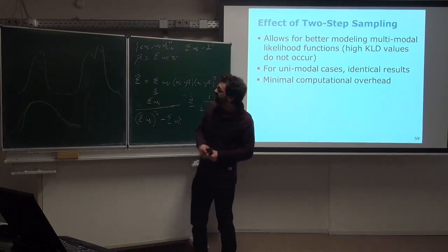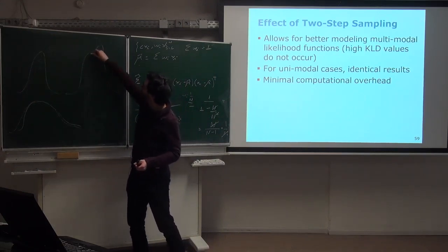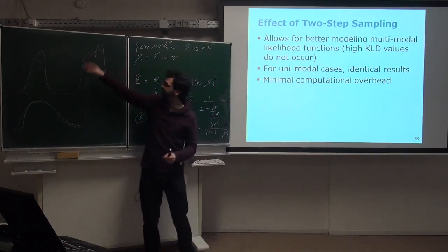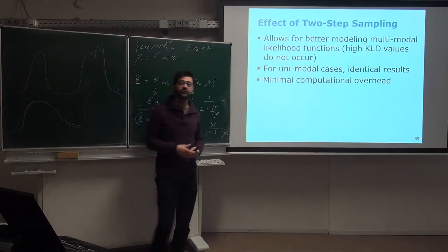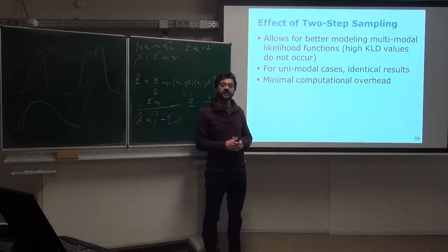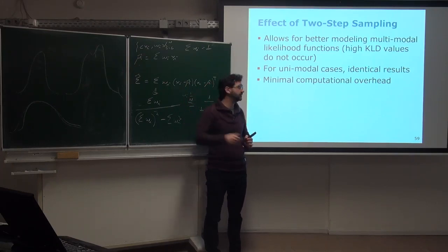In this case where it's slightly multimodal but very similar to a unimodal, you will have some differences. In this case where it's just skewed, you might have small differences but not too much. The reason is that the second step will anyway do a scan matching, so if you end up in the same minimum of your maximum likelihood, you will end up anyway in the same samples that are computed at the end.